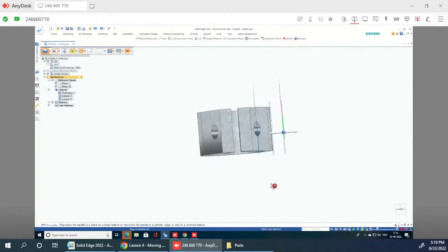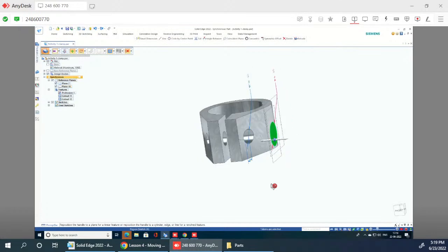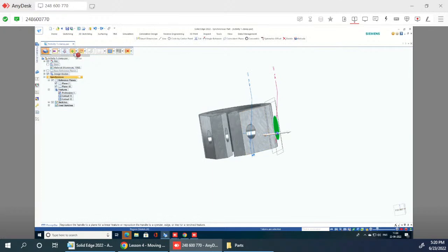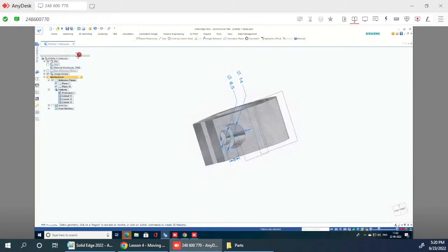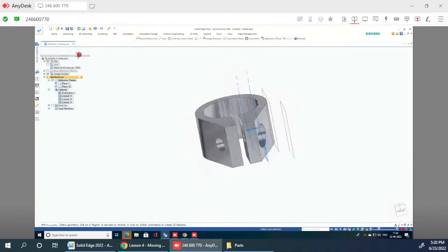So in the top left, you have that option. First, that plus sign is there now here. Okay. So click on that, choose minus or cut. Yes. And now you drag, click on one of the arrows, give the distance. How much distance? Yes. Correct? Now do the same for hexagon on the other side. First you have to displace the plane, then draw the hexagon on that plane, and then do extrude cut of required distance. Okay.